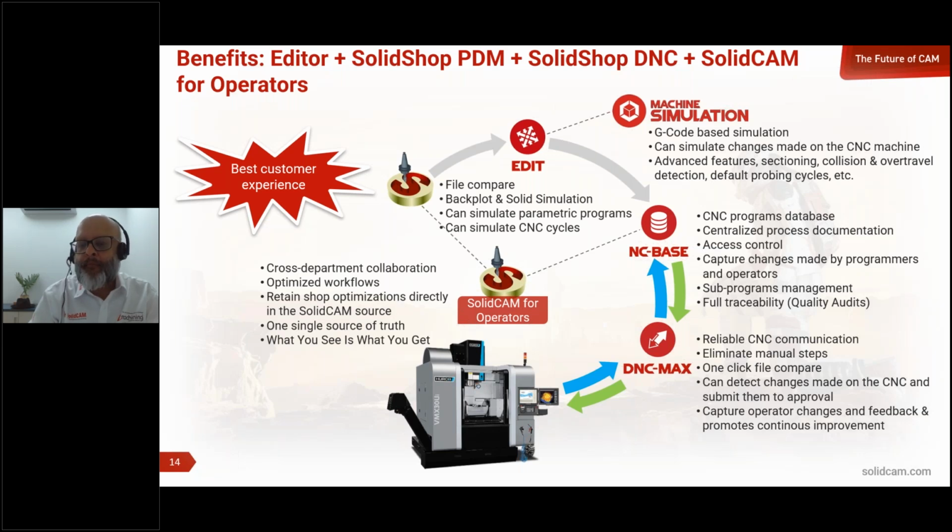Operators can make backups of the SolidCAM file, the PRZ file, before they make any change. They can make a backup in the PDM and then introduce the change they want. Once they close SolidCAM for operators, PDM has an alternate version of that. If the programmer does not want those changes, he can roll back to the previous PRZ file. So it's literally one single source of truth, and that old